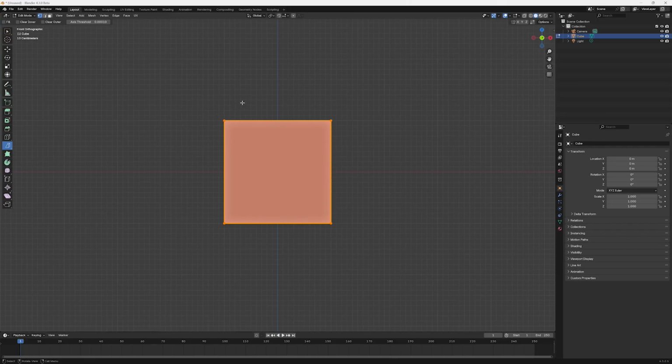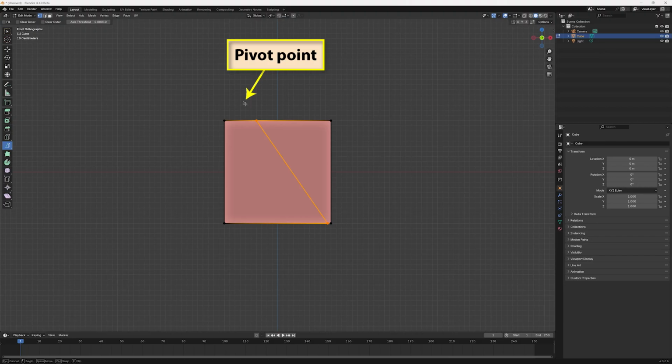Most of the time, we'll just select the whole mesh. When we click the mouse, this sets the pivot point for the cutting tool. Although it will show on the screen as a one-dimensional line, it is more accurate to think of it as a two-dimensional plane, somewhat like a guillotine blade. As we move the mouse, the line rotates about that pivot point. We'll see new edges added to the mesh, where the line passes through selected faces. Hidden faces will automatically be cut as long as they have also been selected.